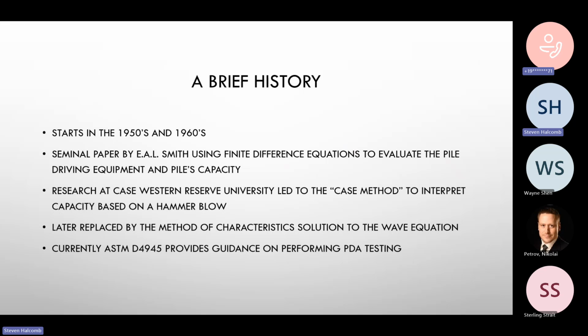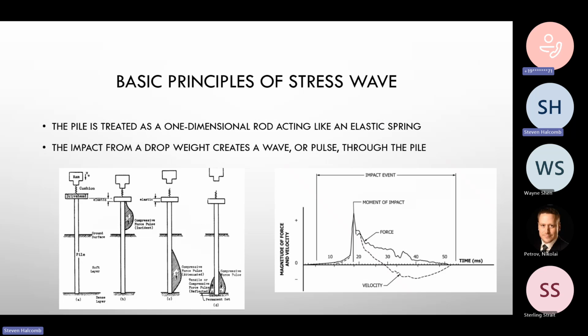Currently we have ASTM D4945, which provides guidance on performing the PDA. And there's a whole host of papers online you can go read. I put a link at the end here. The people that make this equipment are Pile Dynamics Inc. out of Cleveland, Ohio. They host all their papers online. You can find tons of material about PDA, as well as a few other subjects like drilled shafts.